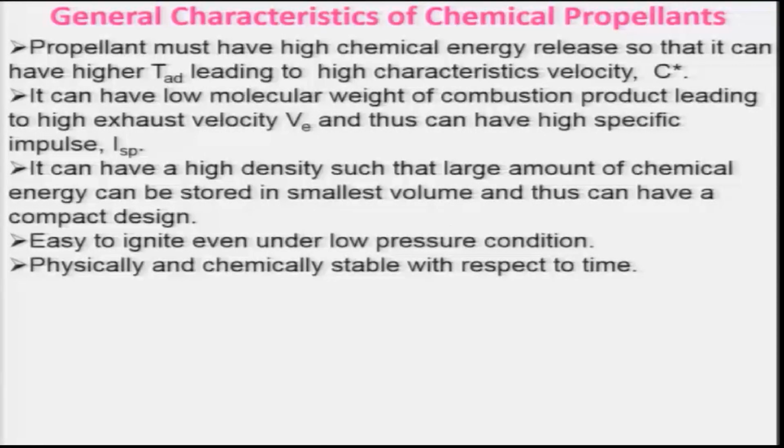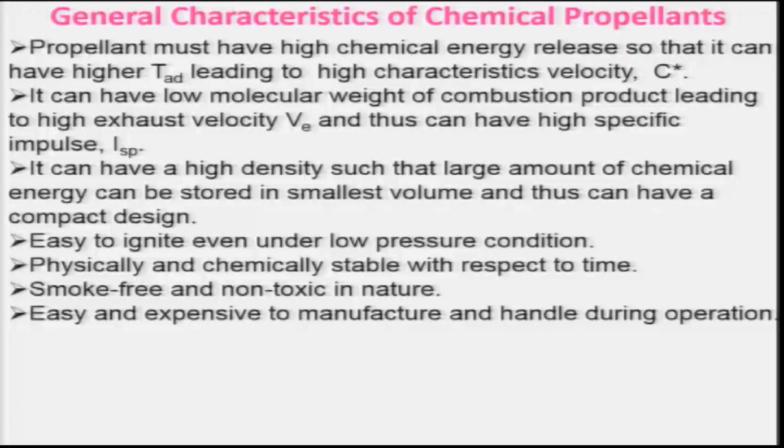So one has to choose a propellant that has a long stable life, and it must be smoke free and non-toxic in nature. That means the gases coming out of the nozzle due to the burning of the propellant must be smoke free or non-toxic, because otherwise it will be detected by the enemies, and it may also affect the people and the environment. So, therefore, one has to choose the proper propellant, one that is smoke free and non-toxic in nature.